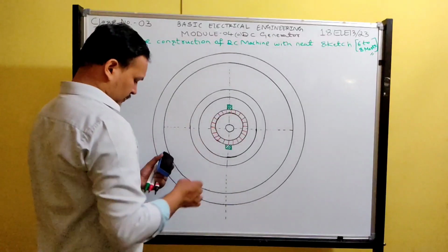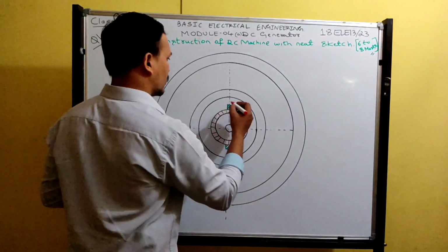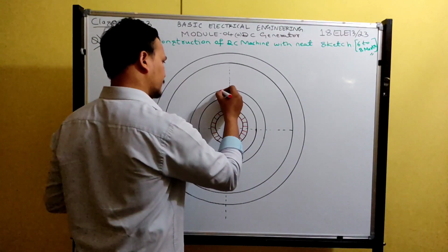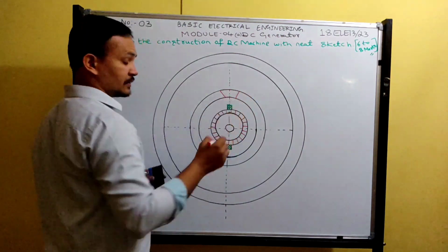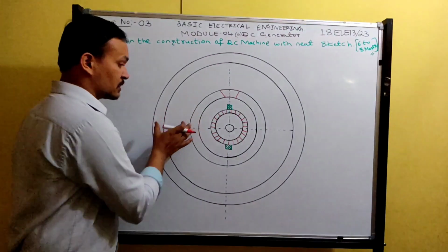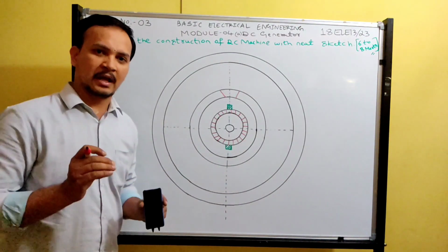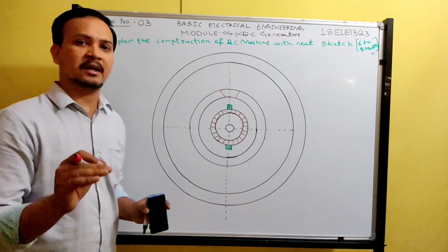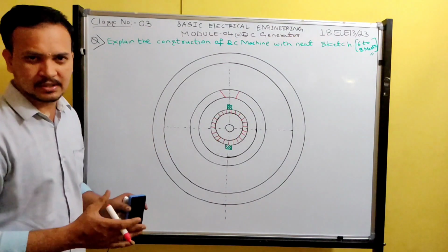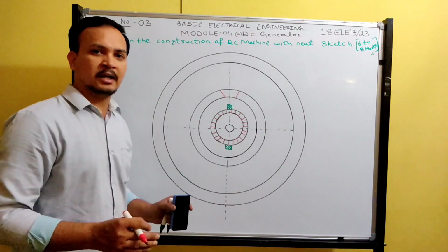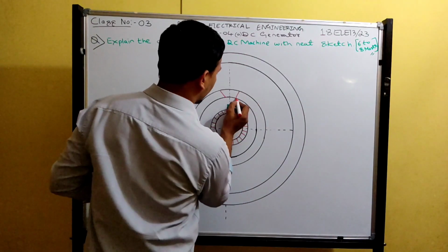After this, next you have to draw the armature core. How to draw that? Look here, observe carefully how I am going to draw. See guys, you should draw all these circles with thin lines. Don't draw thick lines. Draw thin lines, only visible for you, because I am going to do some modifications, so that if drawn lightly, later you can erase it. So draw like this.